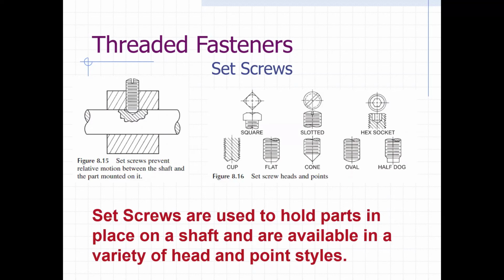If you go to work for somebody that does a lot of rotating parts and attaches pulleys and sheaves onto shafts, then they've got a precedence of the type of set screws and applications they like to use. You just apply whatever type they've been using historically. But just know there are a wide variety of points and head styles in set screws. Set screws are designed to hold things on shafts that tend to rotate.